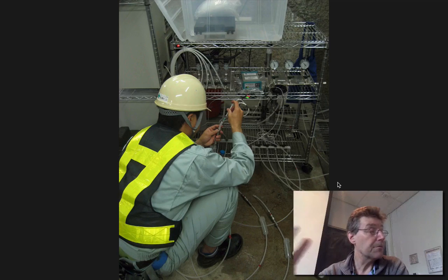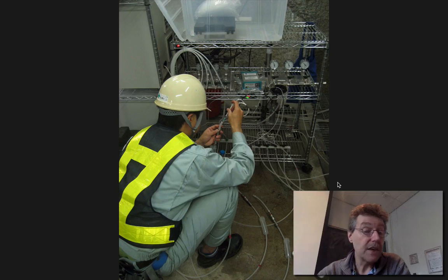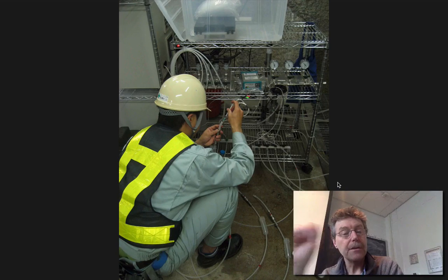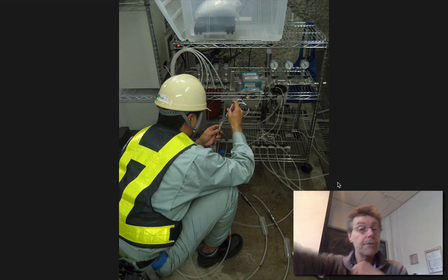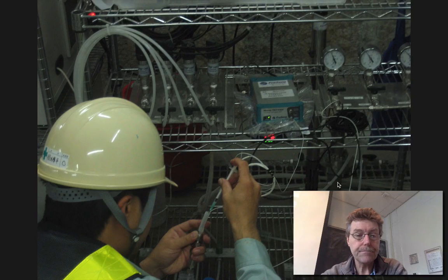Piezometers that aren't any different from the ones that we talked about in this class, that are just a zone that's isolated by packers above and below, or by bentonite above and below, from which you can take samples and be assured that that physical sample comes from that isolated zone, not 400 feet further along the borehole, because you physically isolated that region. So in this case, I think just getting a sample out along tubes.